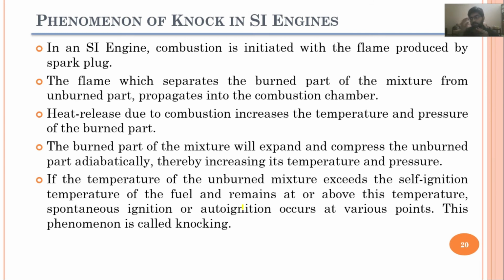So in an SI engine, combustion is initiated with the flame produced by the spark plug. The flame, which separates the burned part of the mixture from the unburned part, propagates into the combustion chamber. We are still talking about the combustion in the combustion chamber.